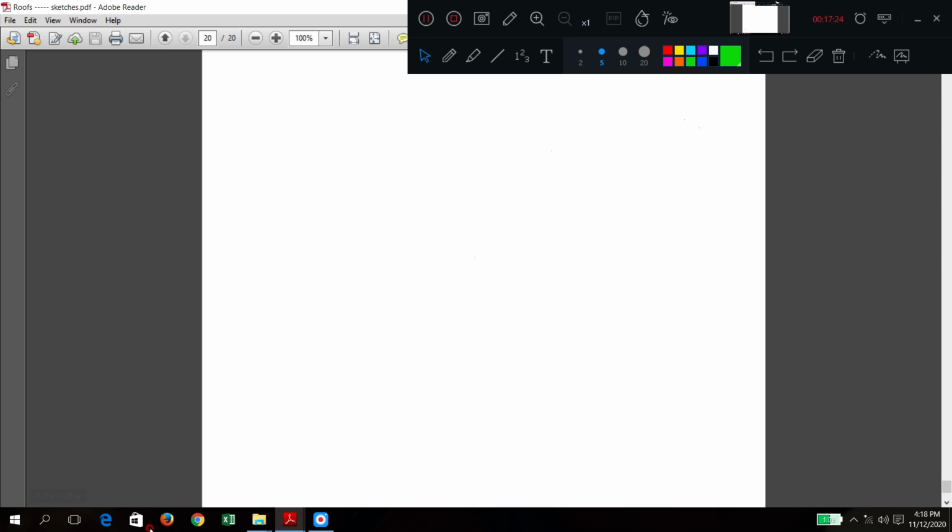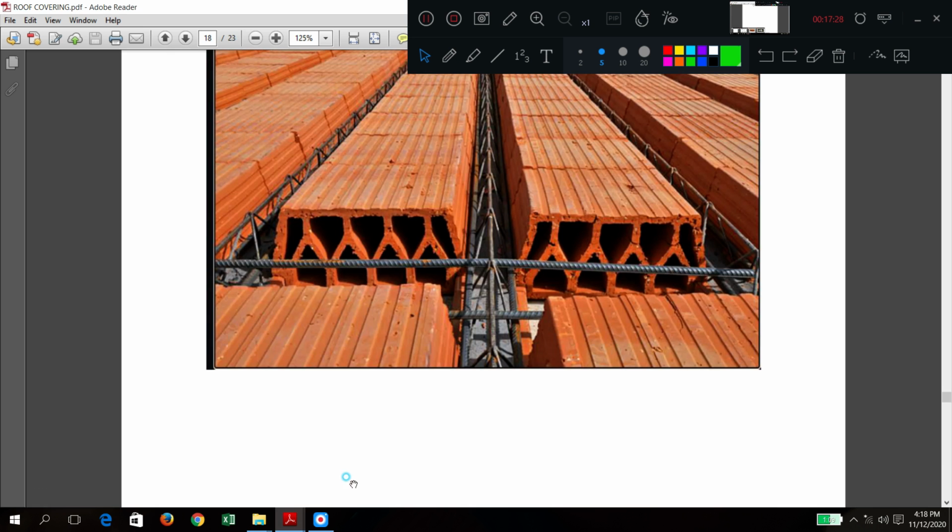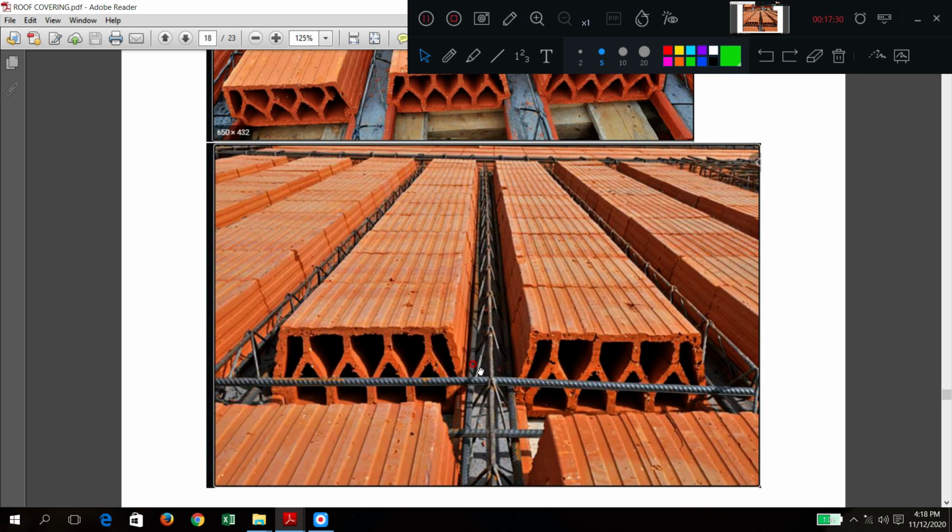What is the advantage here in this hollow one? Material is saved first. Only tension is carried by steel, not by concrete. So the concrete is removed in the bottom section. Only the top cover and these gaps will appear. So much concrete is saved here.